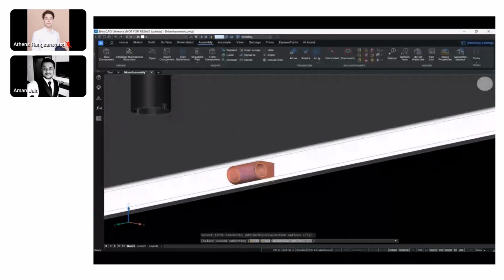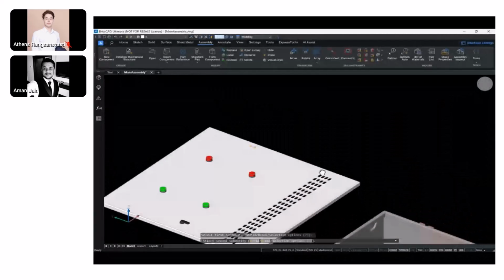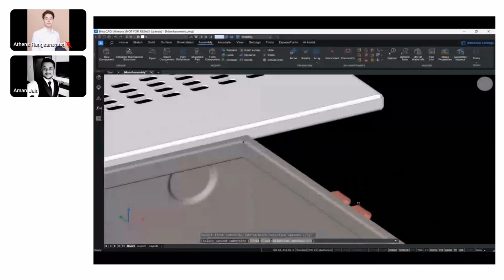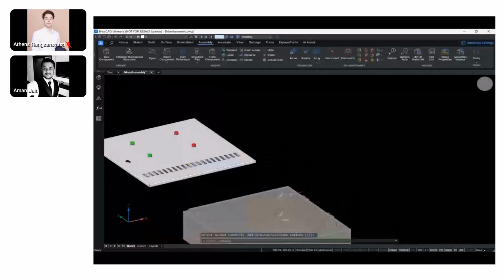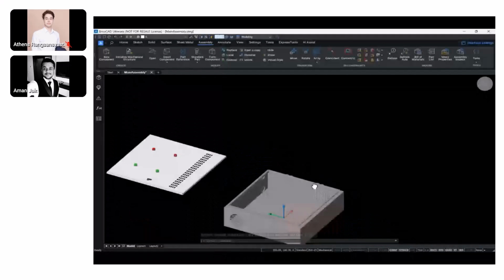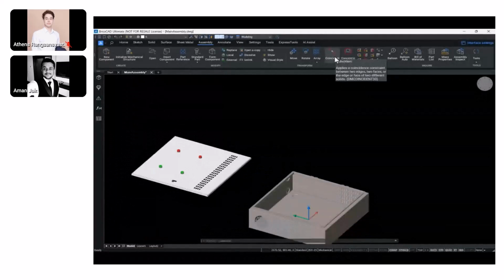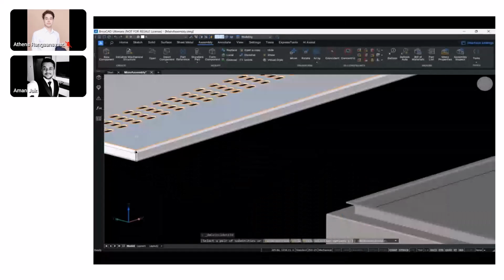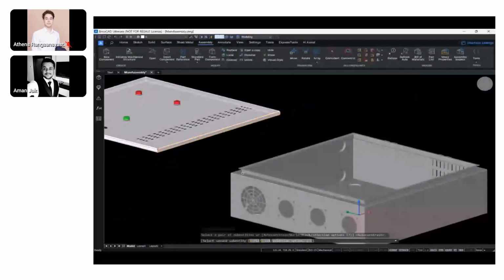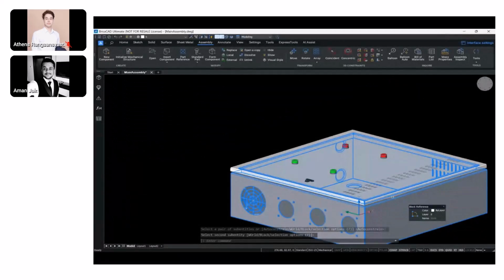Had it been placed vice versa or in the opposite direction, it could have still worked, but it's a bit of a difficult thing for the software to understand how the geometry needs to rotate or what the design intent is. So it's better we keep it constraint ready so that it helps us constrain it very easily. So it's just two constraints that I've applied, and my entire geometry is now constrained.